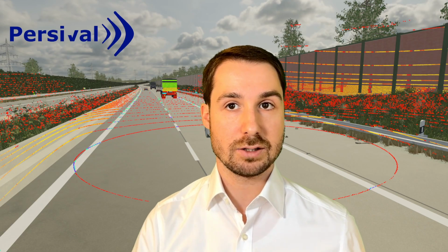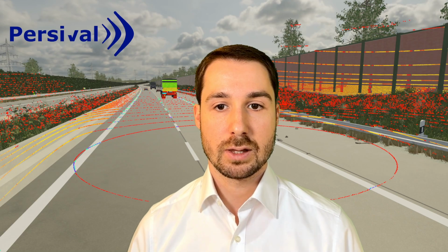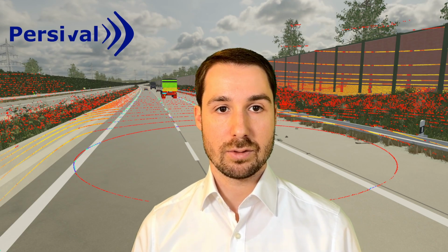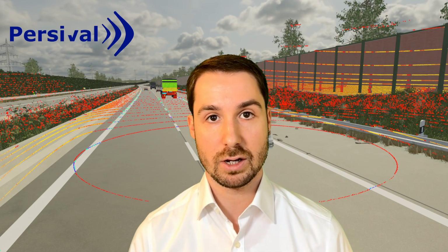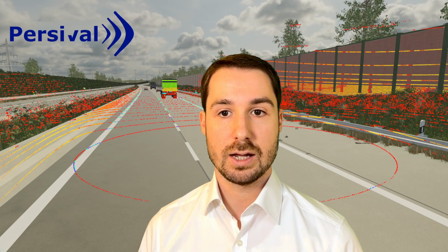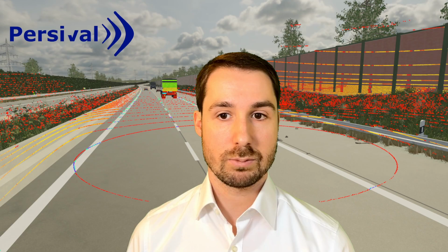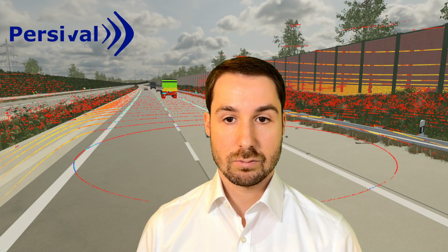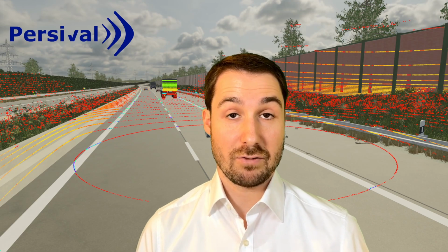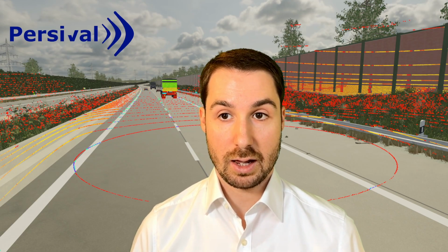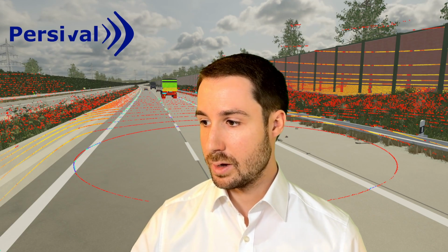And today we're going to look at a very specific class of LiDAR sensors, and that's FMCW LiDARs. And the big thing about FMCW LiDARs is they can measure radial velocity for every individual detection. So every individual point of a point cloud has a radial velocity measurement, and that's measured using the Doppler effect. And of course, if you have an FMCW LiDAR, you want to simulate that effect.